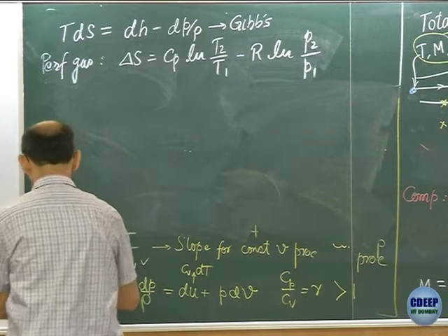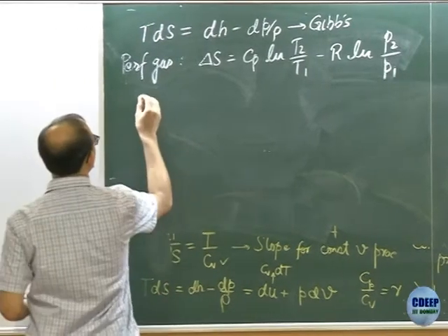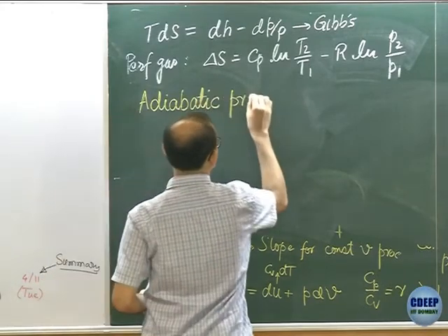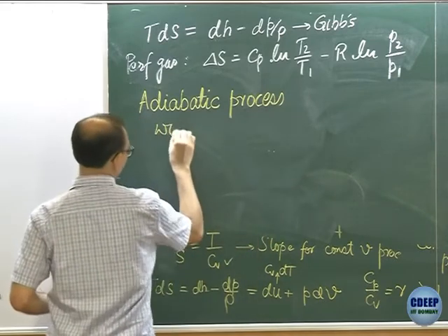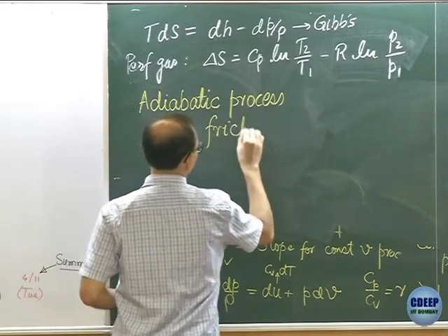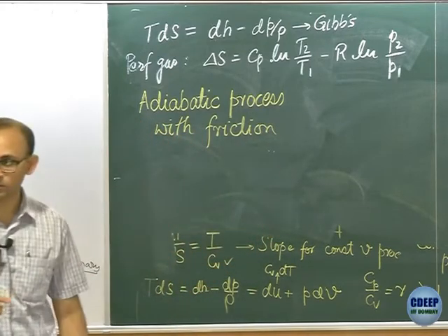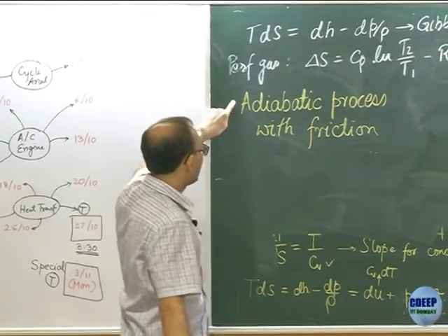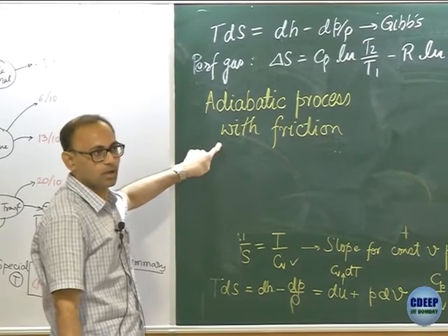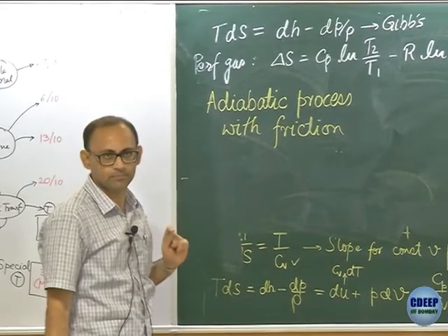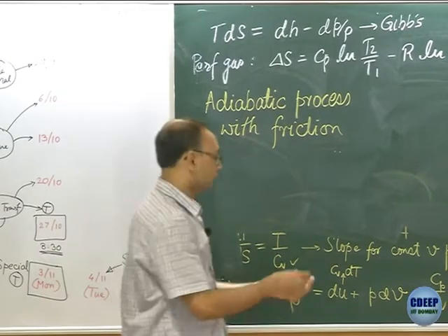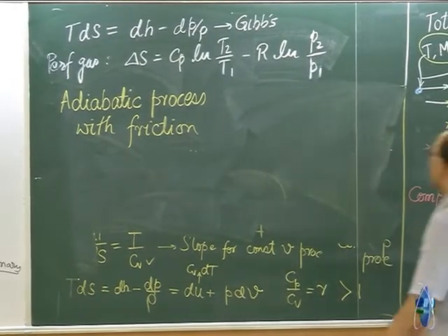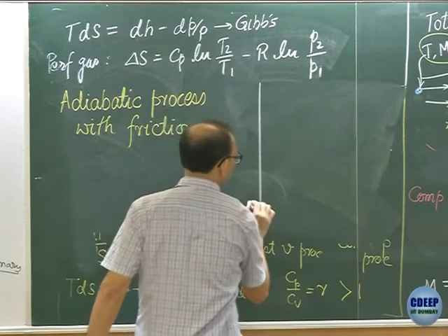If I have an adiabatic process with friction losses. If we have an adiabatic process without friction, then it is isentropic, the straight line. But now I'm saying, if you still have adiabatic, no heat transfer, but if you have friction, how would you represent that on a TS diagram? And that comes very, very often handy in our engine analysis. So, anybody can quickly think about that?